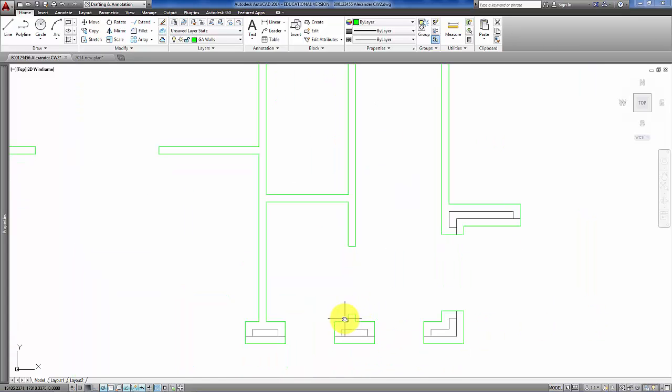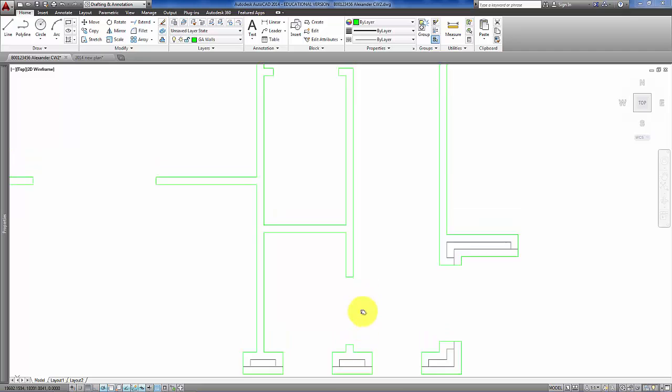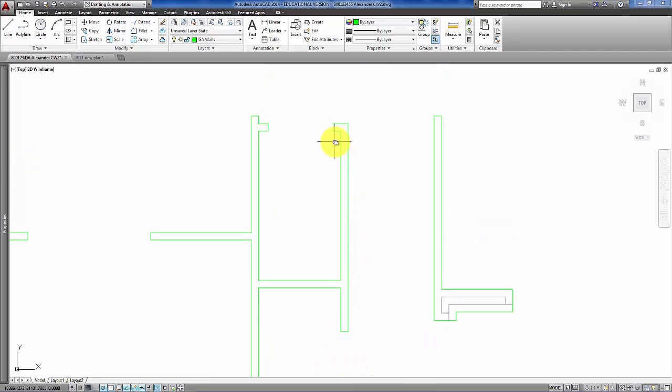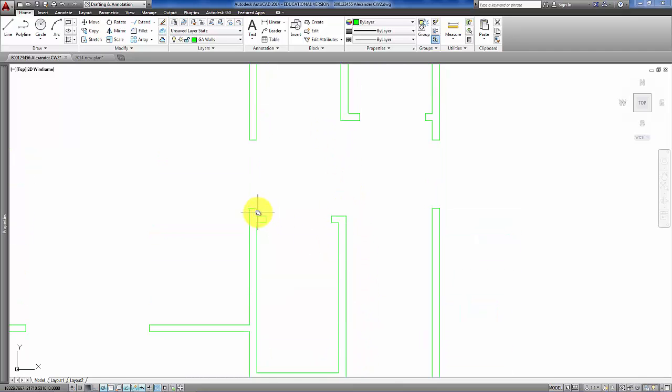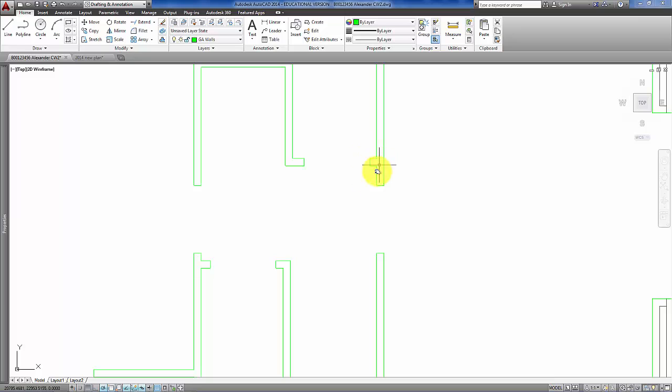Just double check that you have 100mm in behind each of the doors here and here for the WC. The gap at the outside for the dining room door here should be 100. The gap here should be 100, and the door through to the lounge actually lines up with the door into the dining room kitchen area.